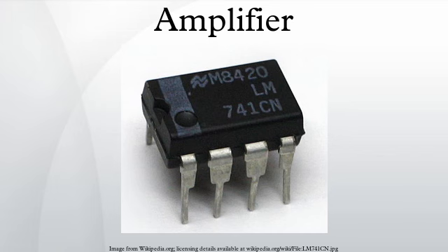When the proper load is used, two things happen. The first is that the output's bias level is clamped with the average output voltage equal to the supply voltage. This is why tuned operation is sometimes called a clamper. This allows the waveform to be restored to its proper shape despite the amplifier having only a one-polarity supply. This is directly related to the second phenomenon: the waveform on the center frequency becomes less distorted.